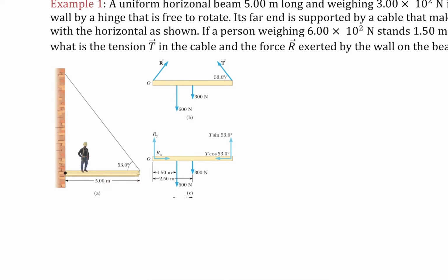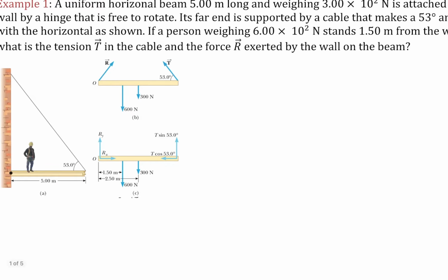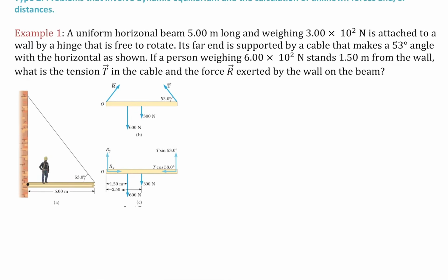All right, and we'll get used to the technique of solving problems like this, but this is a good one to start with. Okay, so what should we do first? Write the sum of forces and torques. Okay, and I should say one thing we should probably even do first, even before we write the sum of forces and torques, is choose our pivot. Because although that doesn't affect anything in terms of our consideration of forces, it's crucial for our consideration of torques.